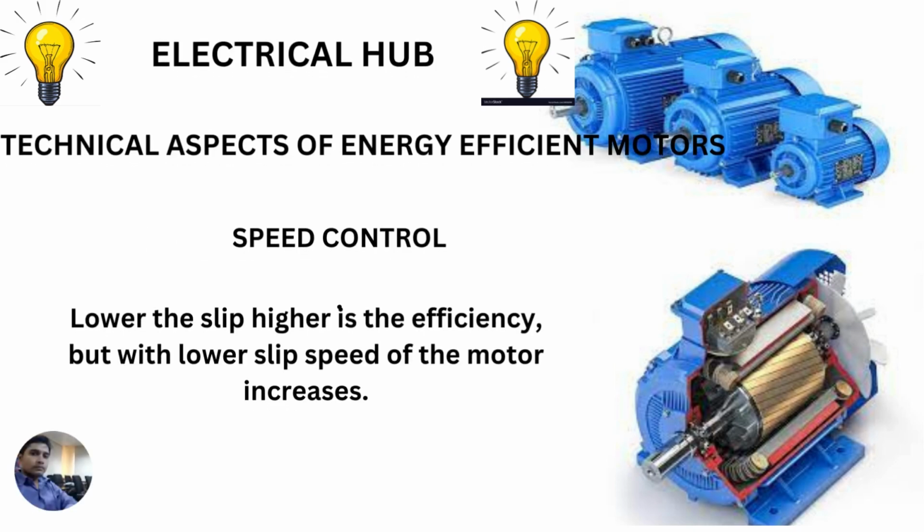Speed control. As we know from the previous video, the slip of the induction motor is equal to (Ns minus Nr) by Ns. So, the lower the slip, the closer the speed of the motor will be to the synchronous speed. The lower the slip, the higher the efficiency. But with a lower slip, the speed of the motor also increases.